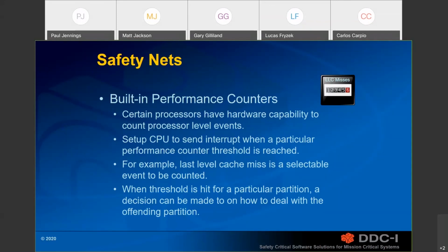One of the key things to remember about this is these hardware monitors are the least tested part of the CPU. So you have to look at the errata, be very diligent at looking at that for these particular hardware architectures, because there are things that you can do and can't do, and that's where most of the errata is in the CPU. So just be careful.